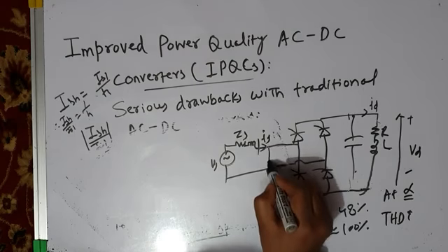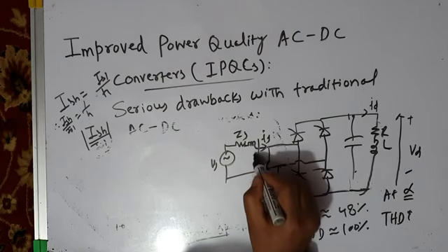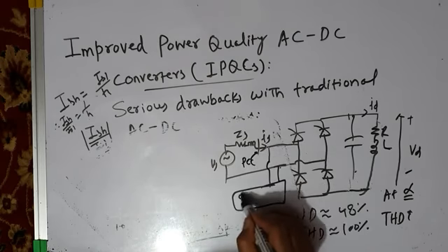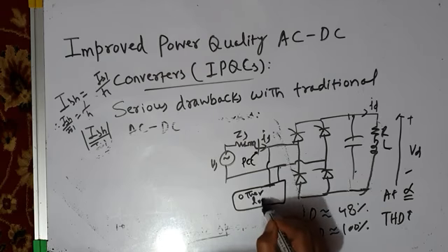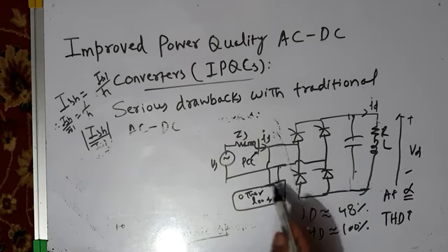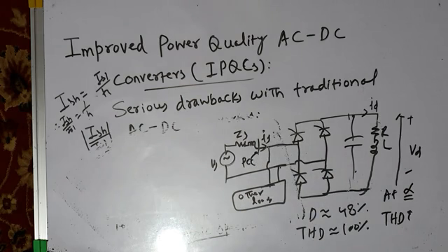As a result, at this point of common coupling, where other loads, other consumers, are also connected, those loads will receive distorted voltage. So distorted current causes distortions in the voltage at the point of common coupling, and as a result the other loads get distorted voltage and they also suffer because of non-sinusoidal voltage.